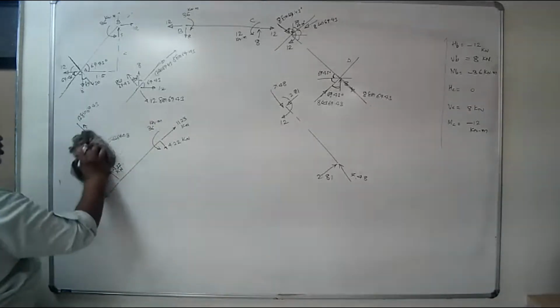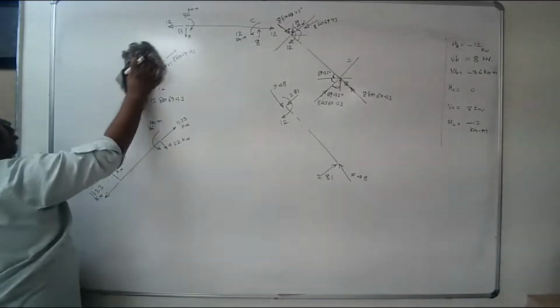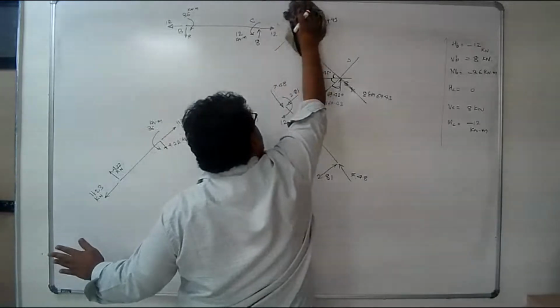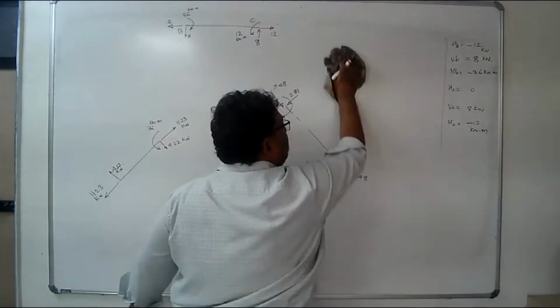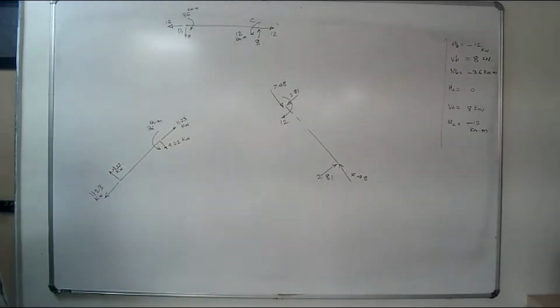Correct, nothing very difficult, but when the member becomes inclined, all those forces, vertical or horizontal, we need to resolve along and perpendicular. So we have resolved the forces along and perpendicular. Now we can sketch the axial force diagram, shear force diagram and bending moment diagram.